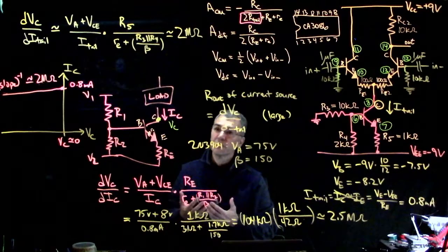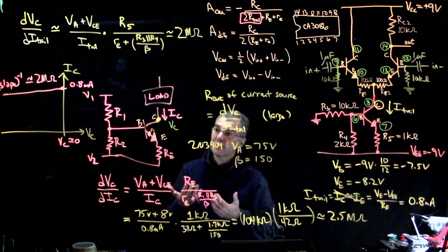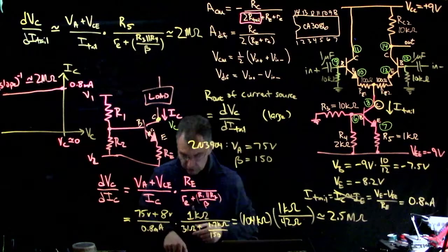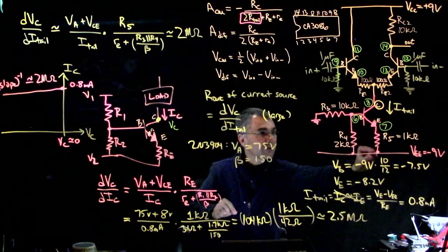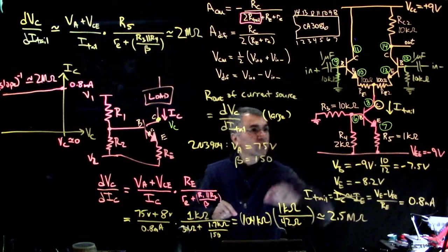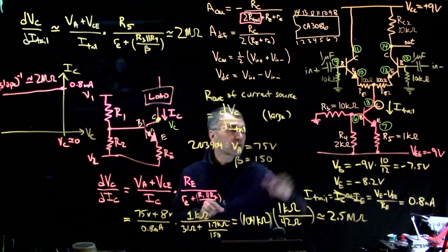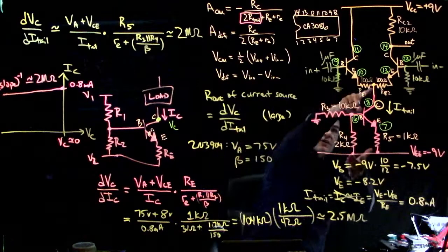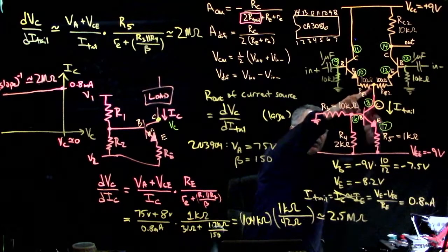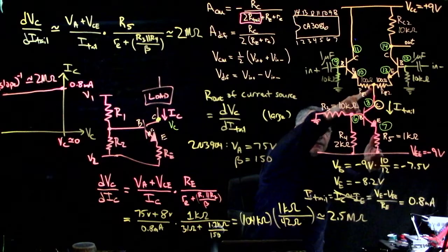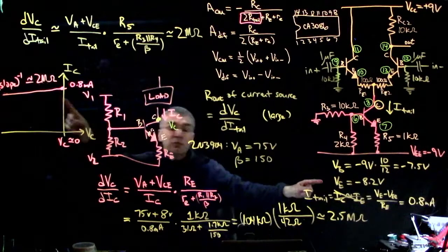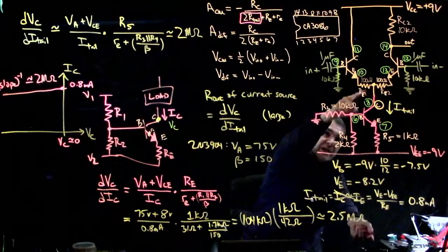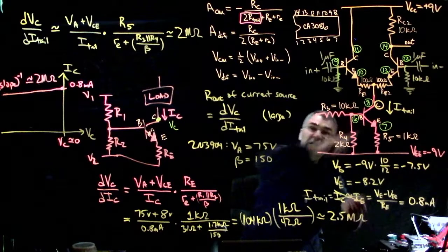With the resistor, the voltage across it is 0 volts when the current through it is 0, which implies that if you want this current to be a milliamp, and this slope to be the reciprocal of 2 mega ohms, you have to put this way down here at minus 2,000 volts, and that would be incredibly inconvenient.